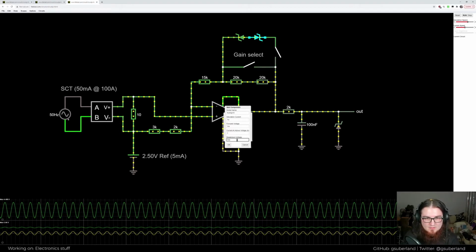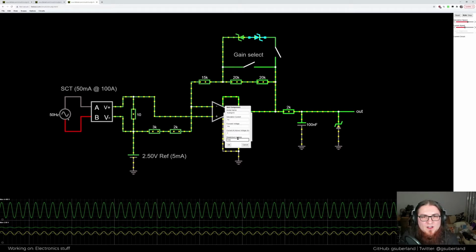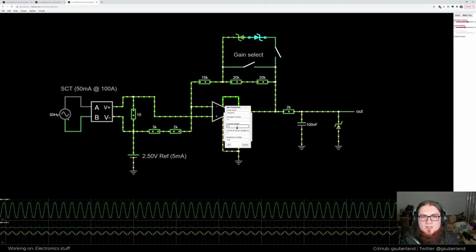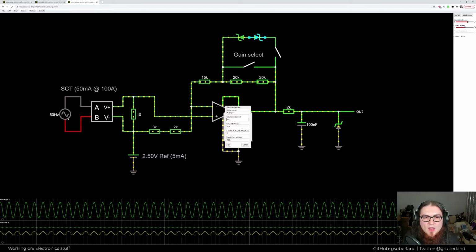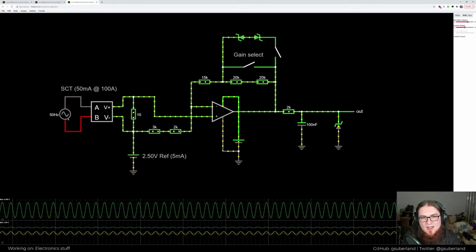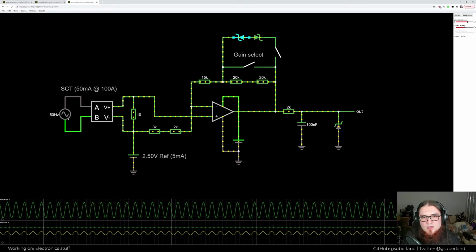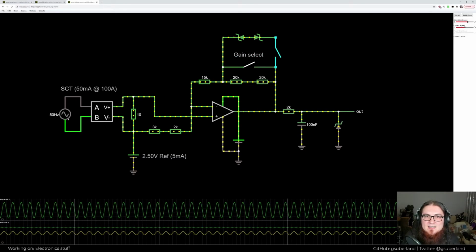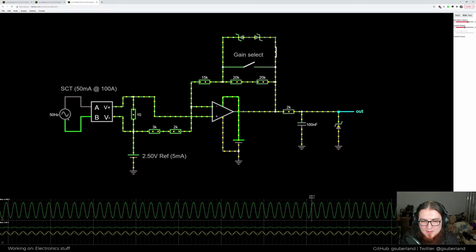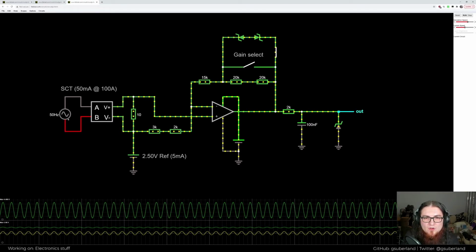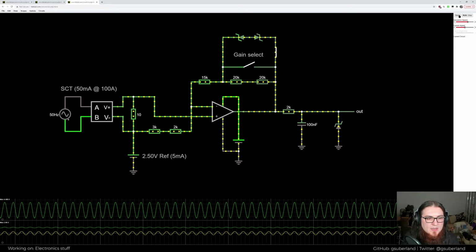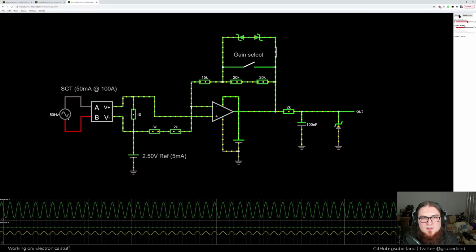We're only passing 4, at absolute peak could only be 5 volts because we've only got 5 volt supplies. And I've set the forward voltage to just be 1 millivolt. This tiny forward voltage, so we don't even care about that. But the saturation current is set to 1 microamp, which is the same as the leakage current. So what happens is when a voltage is applied over here, you do get this leakage current, and this simulates the same effect. So when I turn this on, you get this leakage current passing through. And what happens is that the waveform on the output actually changes due to this leakage current. So normally you get a peak voltage of about 4.406 volts.